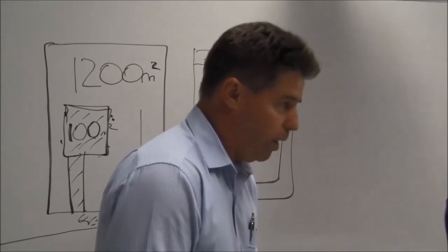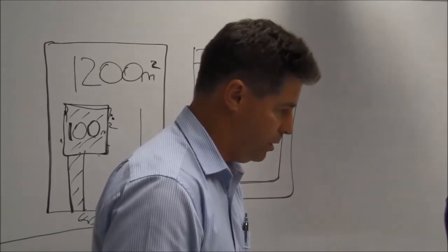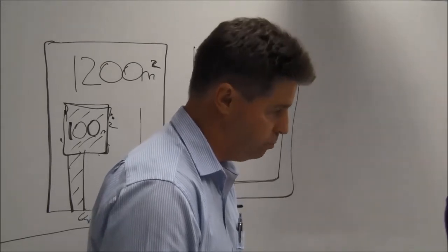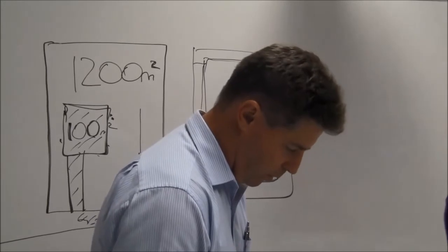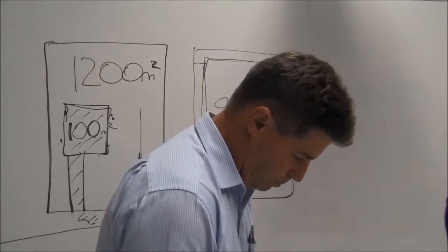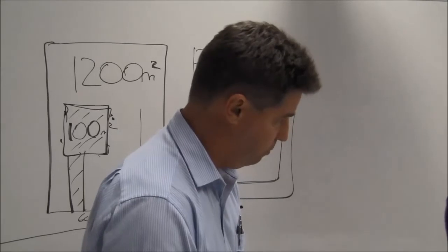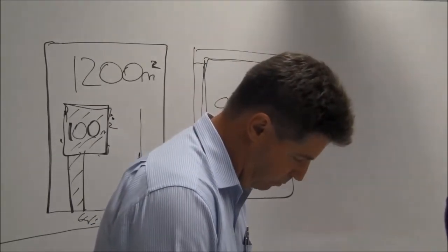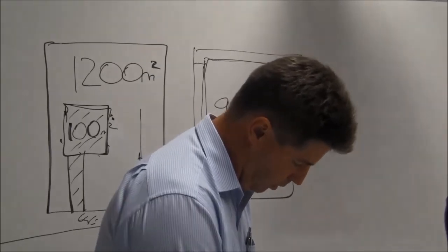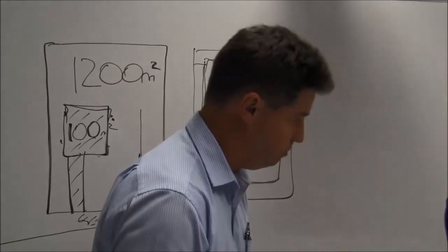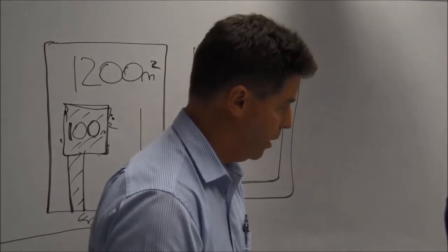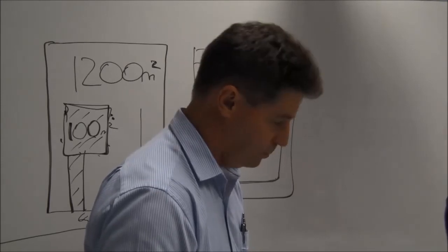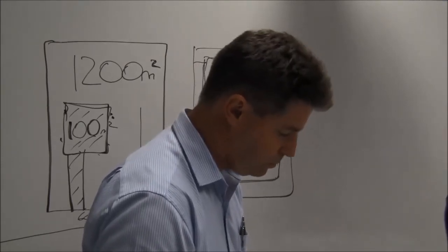We work out what our 1 hour 10-year ARI is, or we just go to Bureau of Meteorology, put the site location in, and find out what it is. If it was 60 millimetres for the 60 minutes, for that 1 hour, and we have 0.85, our fraction impervious is somewhere here, so we just interpolate between the two, and we end up with maybe 0.85 is our fraction impervious, or our CY value. Does that make sense? Mm-hmm.